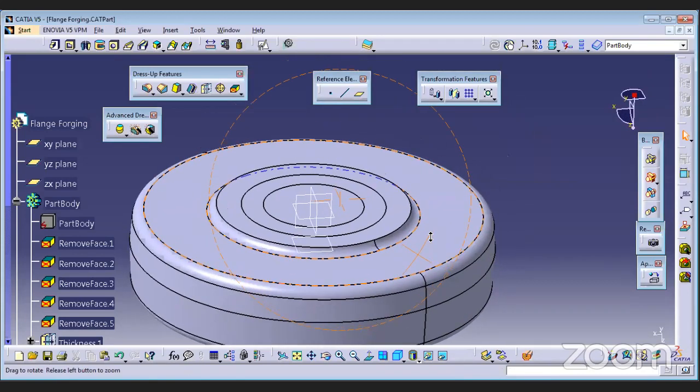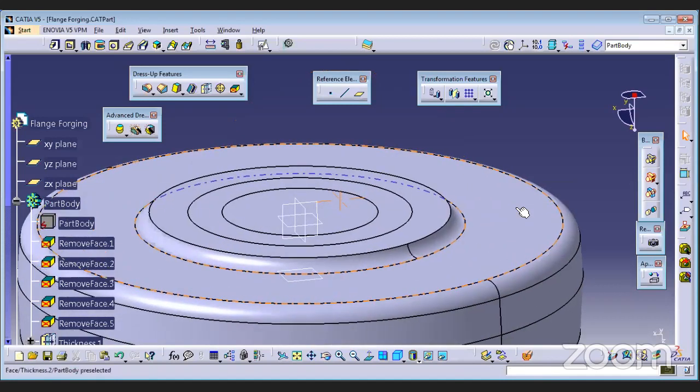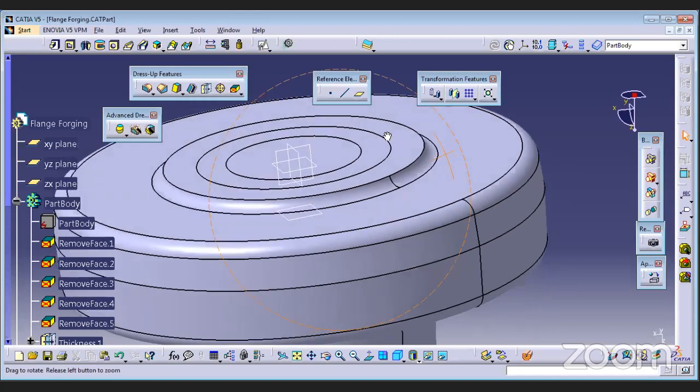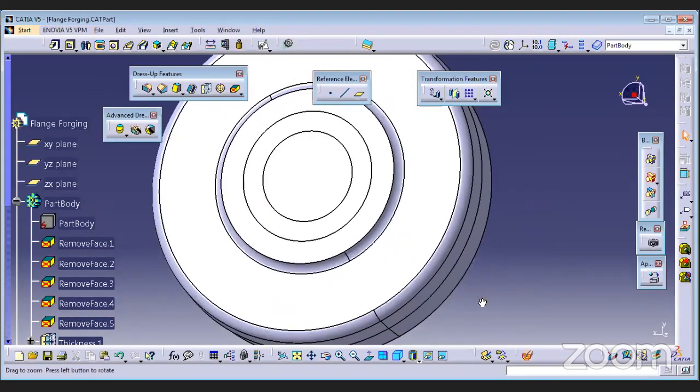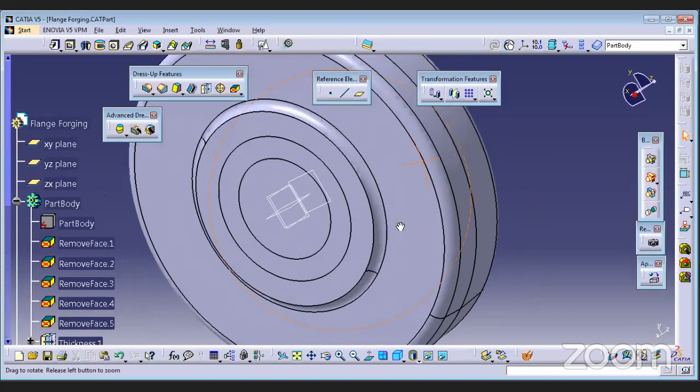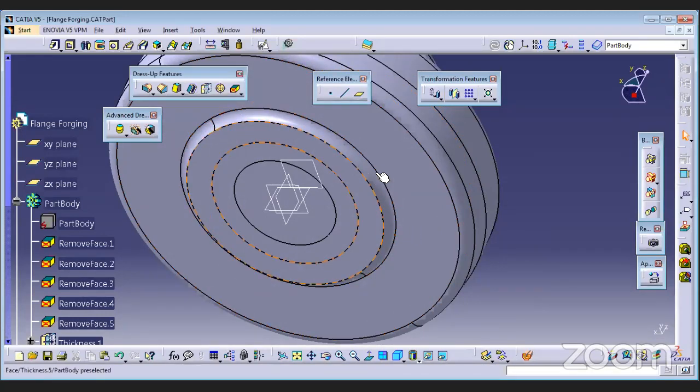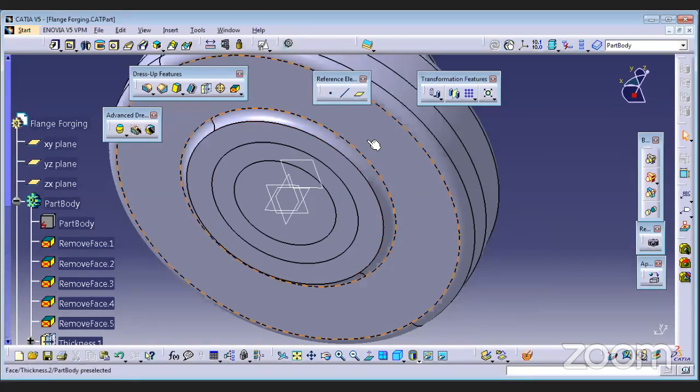Okay. There are different options for circle creation. If you revise your geometry knowledge, we can create a circle of center and radius form, or we can create a circle using 2 points and radius option also. So here the software has used 2 point and radius method, right? So this is the first point. Here tangency option is there and radius is also given. So it will change the different method of